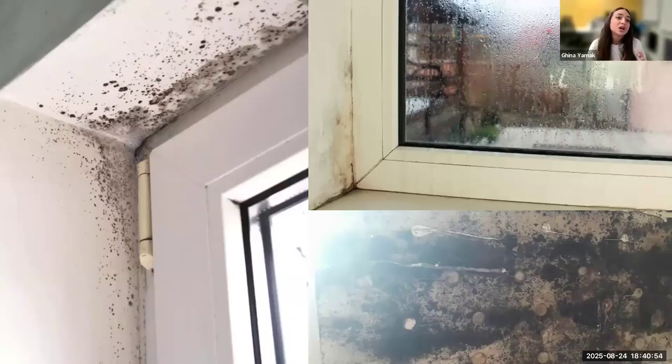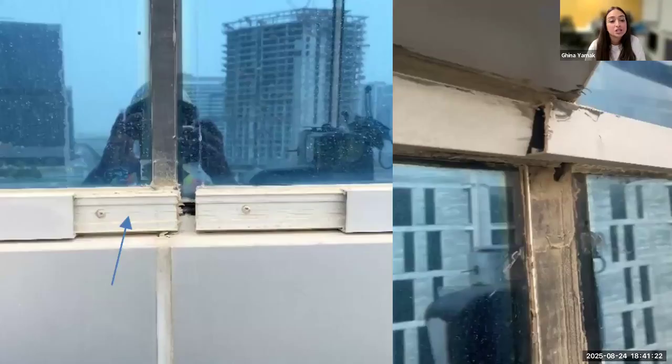So those are images from consequences of bad installation that allows the water in, or allows accumulation of humidity into the glass or around the frame, where there's no insulation, for example, or maybe there is insulation, but the water barrier is not there, or it's not installed right. So this is what you get. You get fungus, you get really bad conditions.